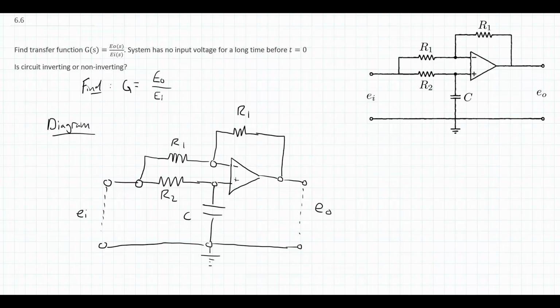Okay, so I've copied down the diagram that we're going to be able to add some extra information to, because in this type of problem with the op amps, I like to use the nodal voltage drops. So I like to mark all of the voltages at all the nodes and then start putting in the currents. All right, so I'll start with the easy ones. Because I have a ground here, I know that the node directly touching it is going to have a voltage of 0. And any node that is directly wired to it will also have a voltage of 0. So those 3 nodes, I'm going to copy that those are all 0. They're directly attached to the ground.